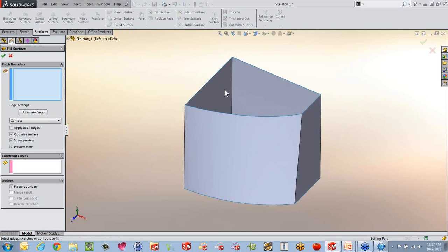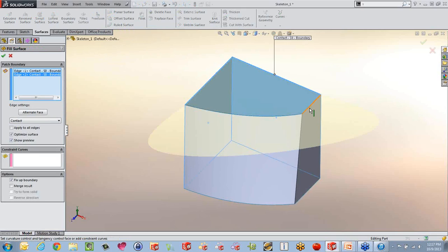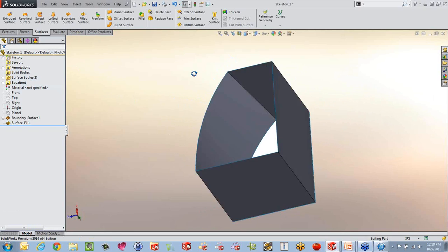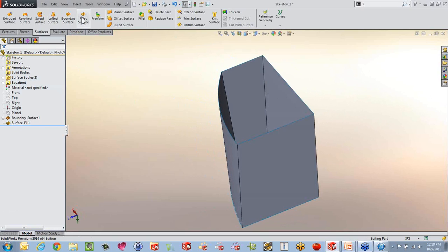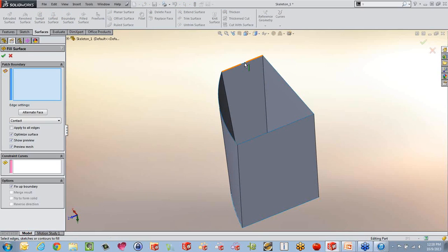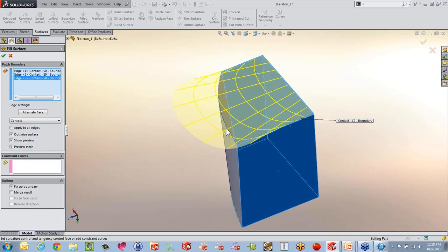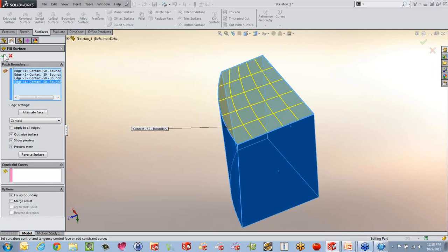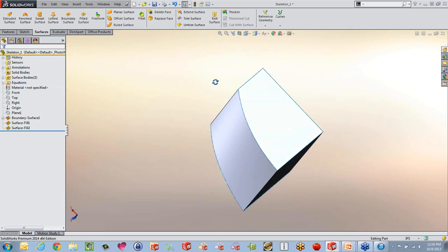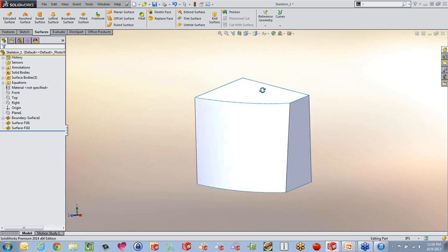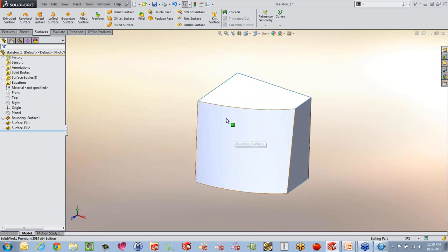I actually like to use the fill command instead. It will do the same thing, and it's much smarter. I'm going to talk about the fill in a little bit. Just select the different edges. You see how it actually gives us a grid sign here, and I could do the same thing on the bottom. So what I have done with this is that I'm not really having SOLIDWORKS trying to figure out all the different edges, right? I'm building right on the skeleton on a 3D sketch, and my design intent is withheld.